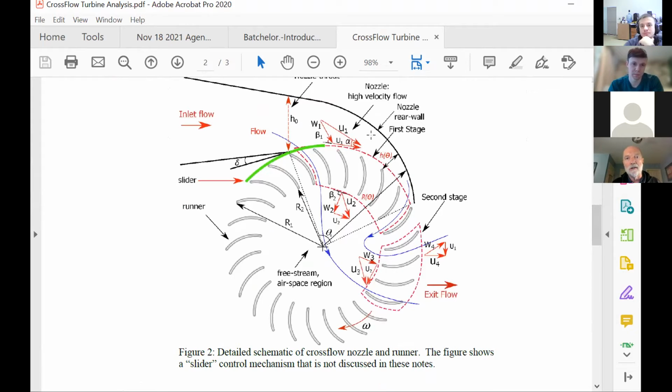And I talked about the nozzle, which is, I can't use a laser pointer in PowerPoint, but you can probably follow the cursor as I follow the nozzle. The water comes in to the nozzle and the nozzle distributes it to the blades. And the blades are combined on a hydroturbine called a runner. That's the English term for it. The water then exits the turbine, and we've done a lot of computer models of these turbines, and the exit area, the exit flow, seems to always be very close to the inlet flow for reasons that we don't entirely understand.